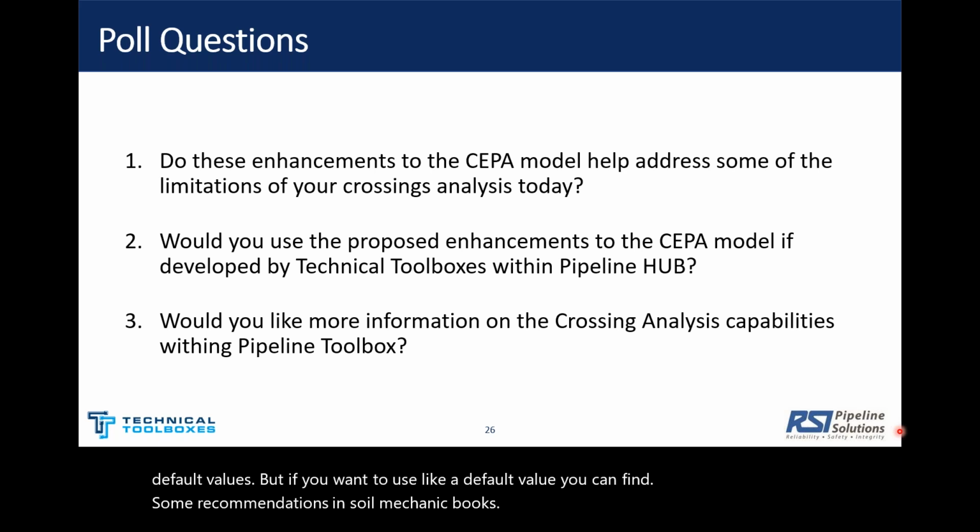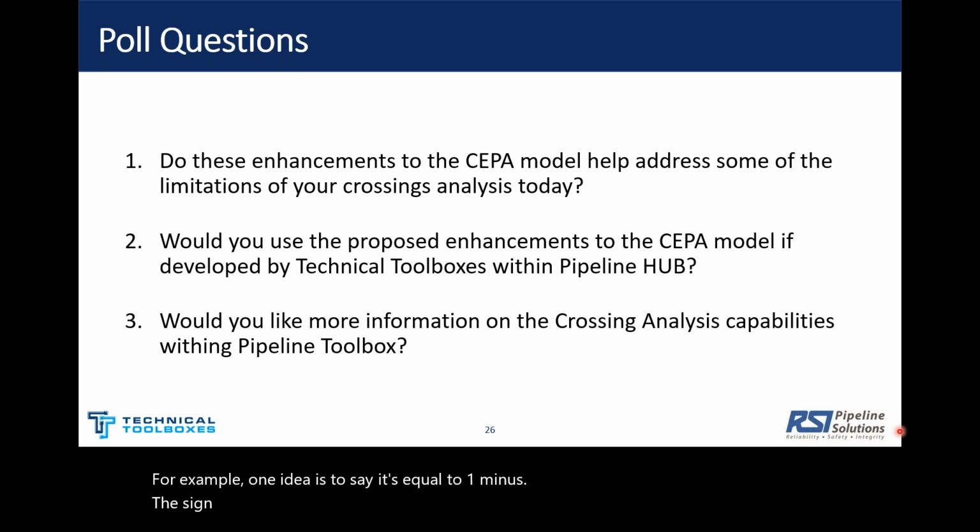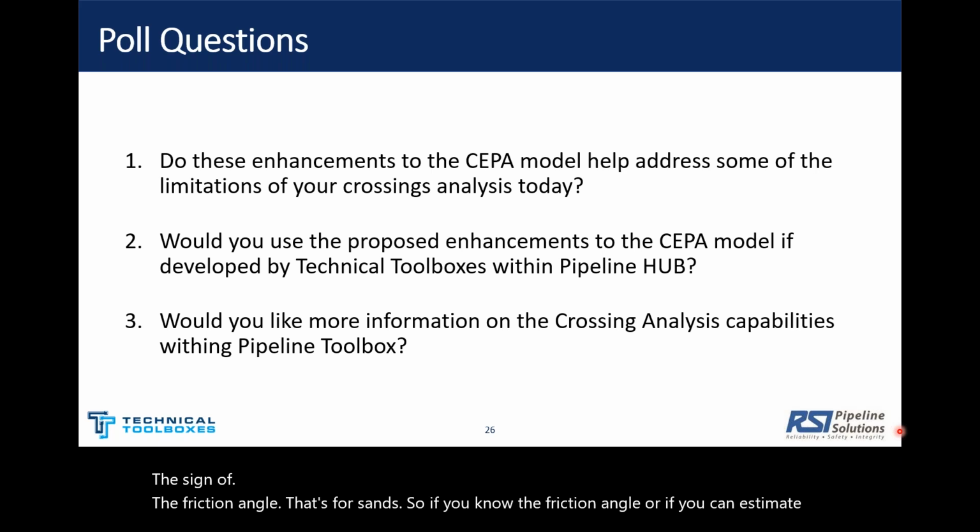For example, one idea is to say it's equal to 1 minus the sine of the friction angle. That's for sands. So if you know the friction angle, or if you can estimate that, you can use that equation.